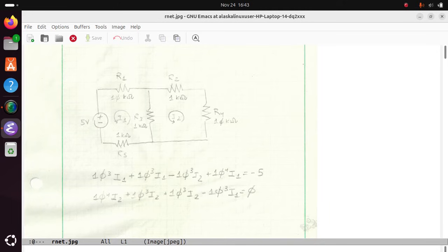pretty simple resistor network with 1 kilo ohm and 10 kilo ohm resistors, and using the loop method, we are calculating the current in each loop, and then that current can be used to solve for the voltage of each individual resistor if we want to. So at the bottom there we have the equations that we come up with as we work through each loop.